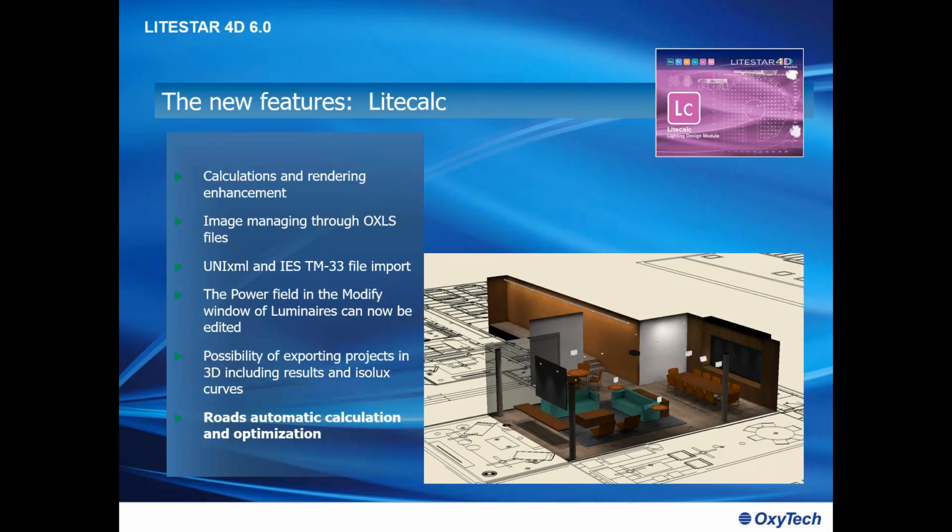It means that you can measure a single photometry, complete photometry, and then you can define the ratios when you pass from, for example, 500 milliamp to 350 milliamp, and define the two values of the current, power and flux, so that it will be possible with the program to insert these values and to create a curve, so that if you need to run the calculation with a 366 milliamp current, it will be possible, and the program will automatically calculate the flux related to such a current level.